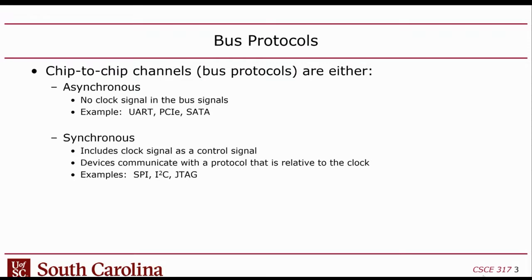But we have an issue with a project I'm working on with the Navy where we have these chip-to-chip links, and we're using one of these technologies that use this encoding and embedded clock. Because these clock synchronization characters have to be randomly inserted, it ends up making the channel have an inconsistent latency. It's unpredictable, non-deterministic. Sometimes it'll be a longer latency, sometimes a shorter one, depending on whether it had to synchronize. Anyway, I'm getting off topic.